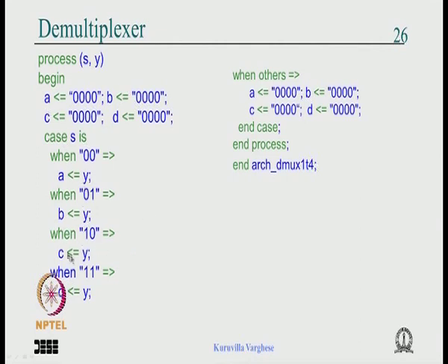It looks at the case statement and understands what structure comes out of it. It is basically a demultiplexer, because depending on the select line, the various outputs get the same input, so that is inferred as a demultiplexer, and it also has to take this initialization part into account. So this works perfectly fine, but you shouldn't take liberties with synthesis.